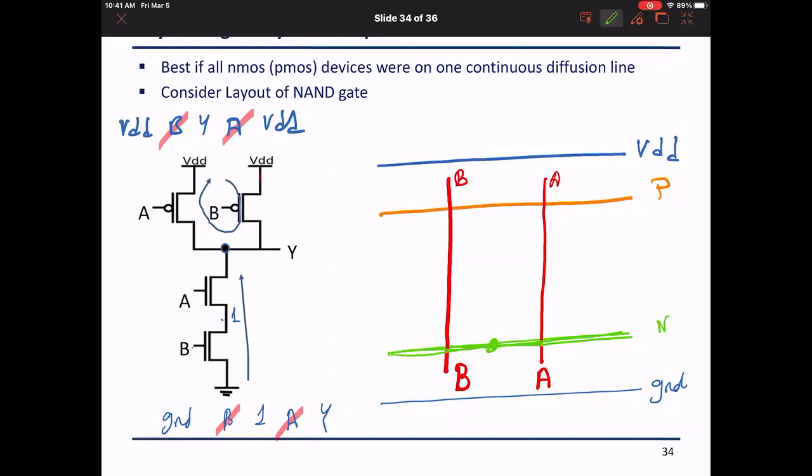Yes, supposedly. So this continuous strip, when I follow a single path that will go through the diffusions, why? Because it goes through source and drain, cuts under the channel, not at the source, but at the common node and that's it at the output. Of course I have a channel here, so this channel can be on or off wherever A and B cross it. But this single path is telling me that when these transistors are on, I am going to have a single path between ground and out, right?